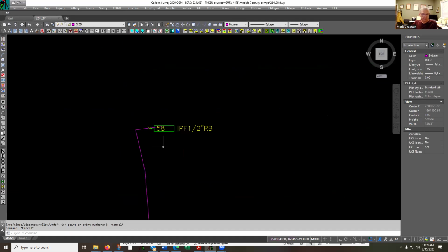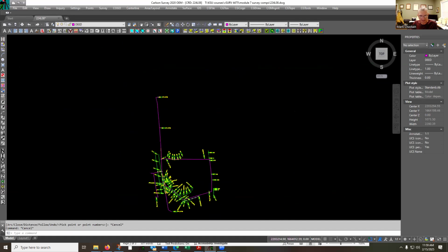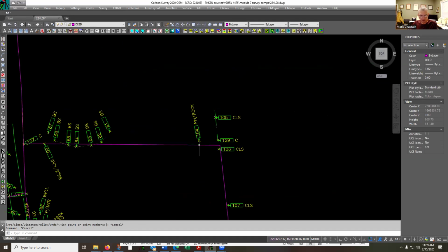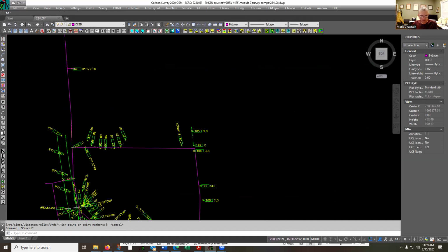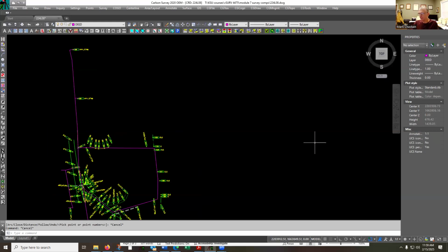At this point, you should have a clue that all of our endpoints and where we're looking for them are to the right of the monuments that we found as being oriented from number 60. This is because our record plat was on a magnetic north, which means it could be within 5 or 10 degrees of north. Might even be more in rare occasions.